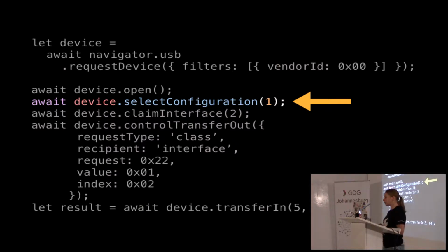A configuration for, yep? Oh, sorry to bother you. So the vendor ID, I didn't know if you said this already, but is that like a standard, like you have to have a standard hexadecimal? So if it's assigned to the company. It's assigned to the company by the USB standards committee. Okay, so it'll be standard across all devices. Yeah. So all the devices from that company will always have the same vendor ID. So every manufacturer that's out there has to come to the standard, even the most random company out there.